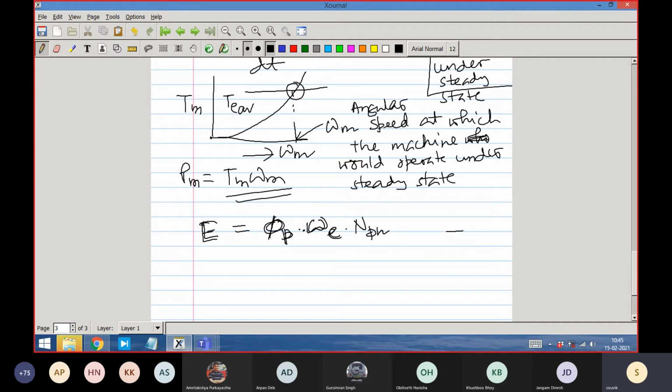Professor has definitely done this derivation, right? A voltage induced in a coil. Hello? Yes, sir. So what is this flux? This is the flux in the air gap. The moment you are applying a voltage, it is related to the flux linked by the coil. And I said that let us ignore for the time being the leakage flux. So the flux linked by the stator coil is the same as the flux in the air gap. So this quantity gets decided, provided omega is constant, and omega is constant. Our supply system is normally more or less constant. Take 1 or 2% variation in the frequency that happens. That is the essence. We are learning essence all the time.